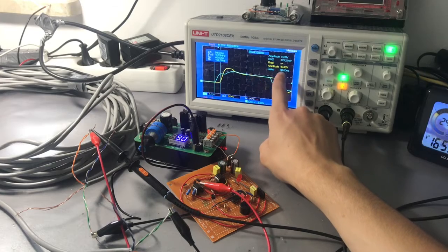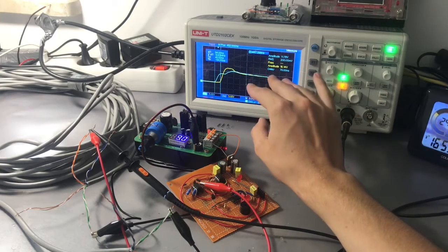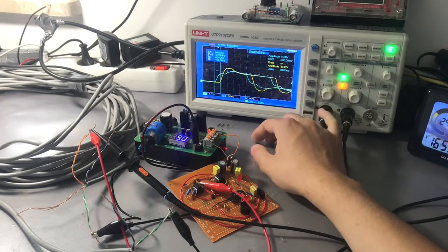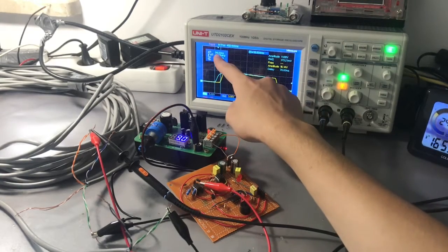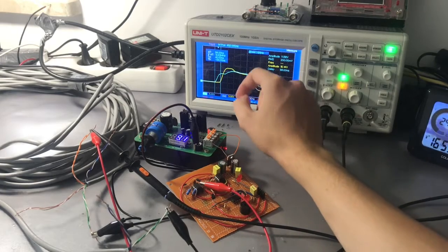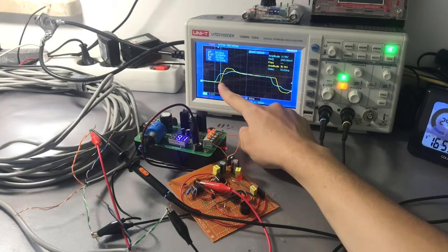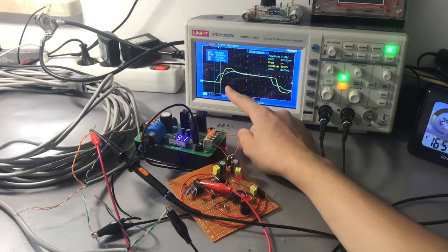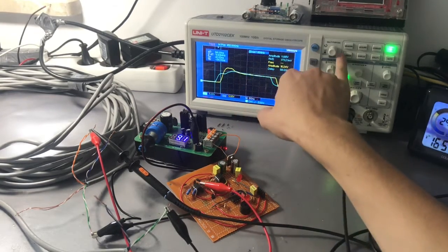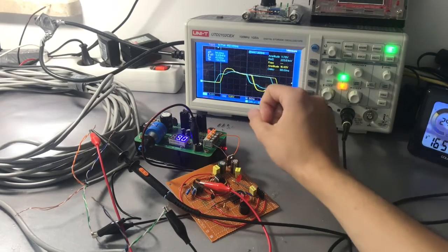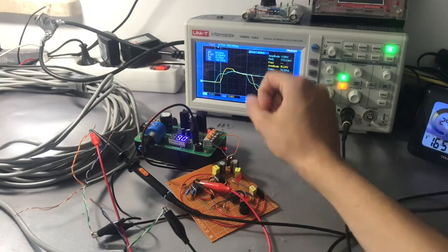Automatic measurement of the scope says that we have somewhere around 70 nanosecond delay. In my opinion, we have a delay somewhere around 94 nanoseconds. And I think that my measurement is a bit more accurate. I used the cursor function, and we have a delay of somewhere around 94 nanoseconds.